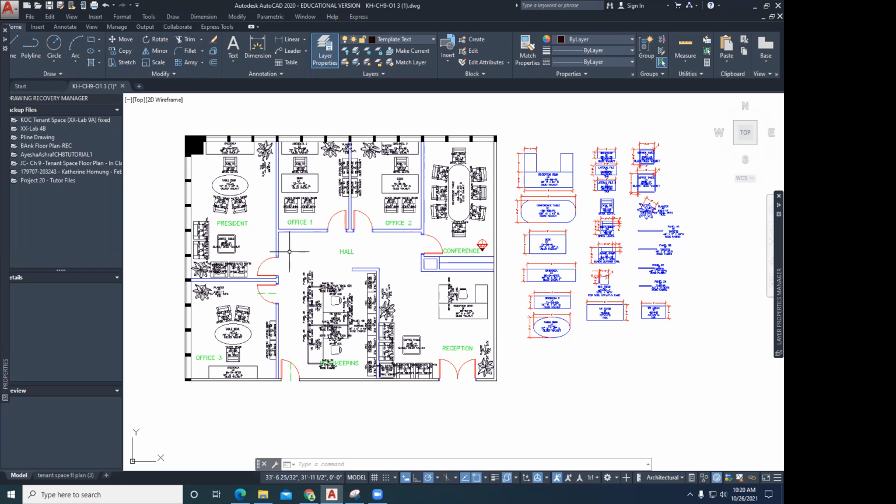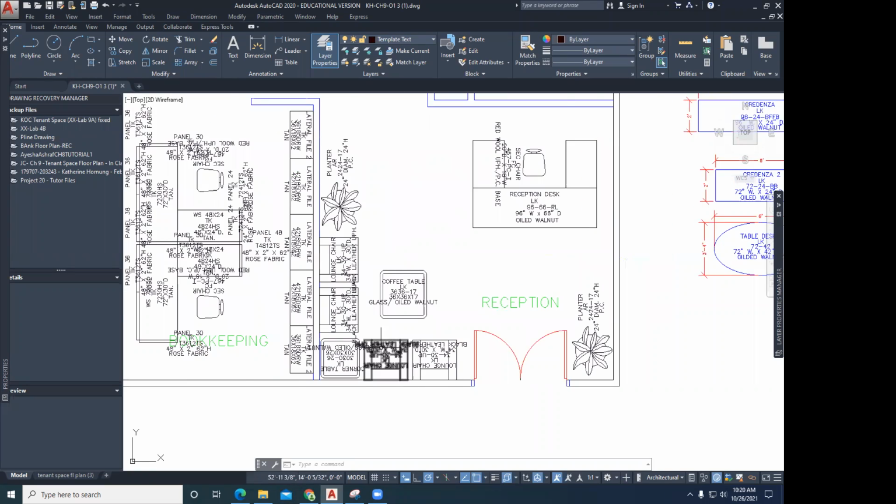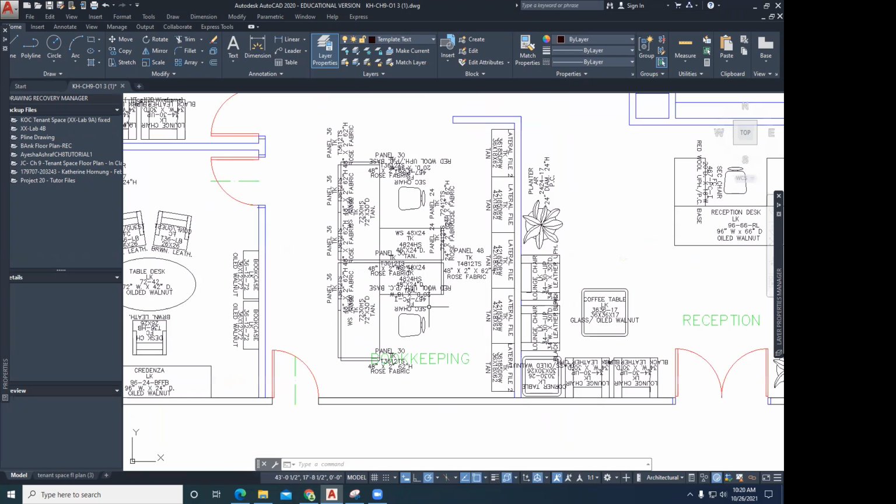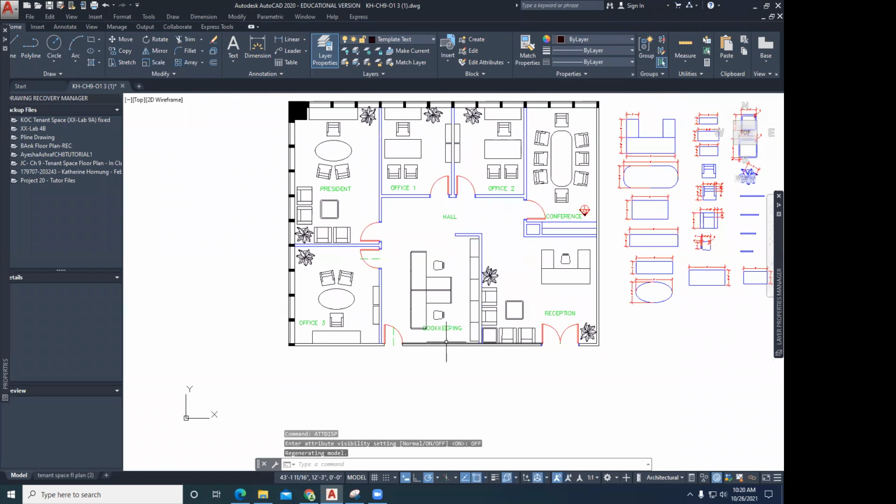Fantastic. As you start to work with things like attributes, you will find that everybody uses them, especially in the architecture and interior design area, because that's going to link you to the furniture and where to get that furniture. It comes across as looking very messy, but that information is for the designers and you can turn it off with ATTDISP, attribute display off. And then we have these different layers within the drawing.